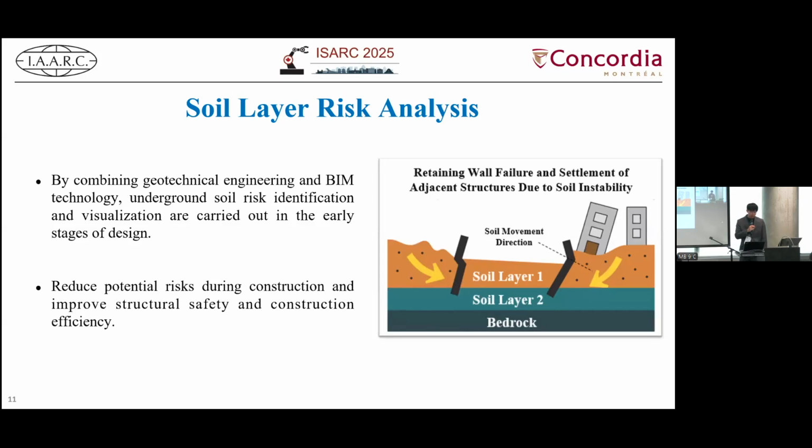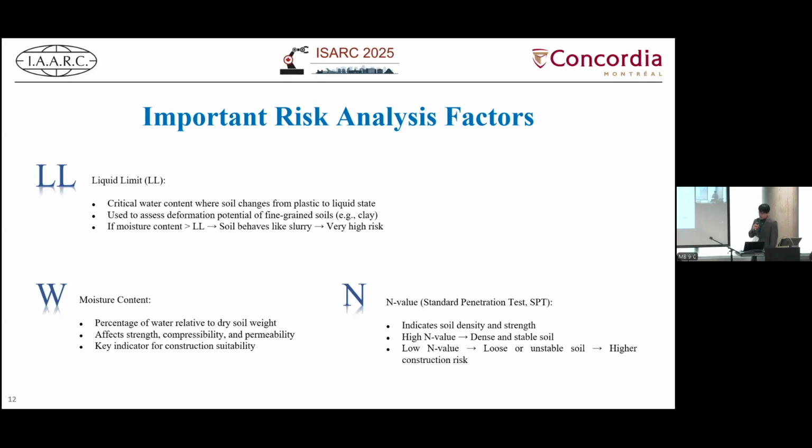After building the main soil model, we integrated foundation engineering with the BIM technology with the goal of automatically identifying and visualizing underground soil risk during the design phase. Next, I will briefly introduce key risk factors for foundation safety. We use 3 key parameters from soil mechanics, N value, water content, and liquid limit.